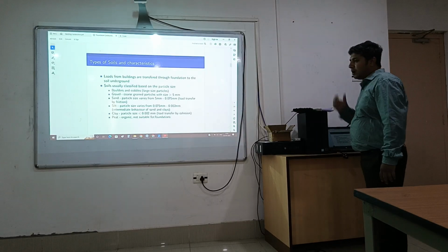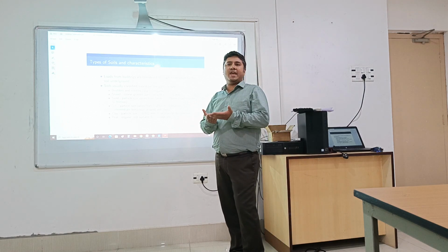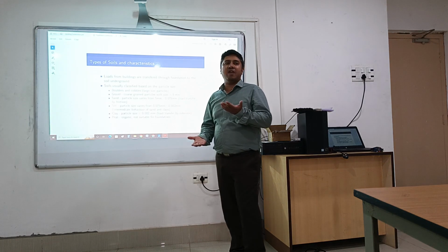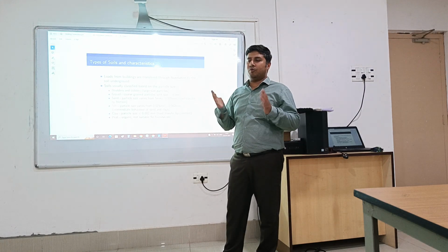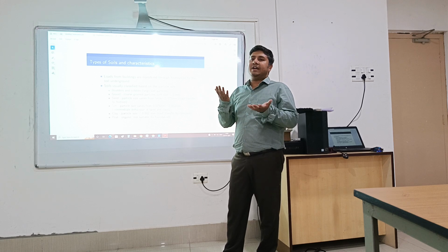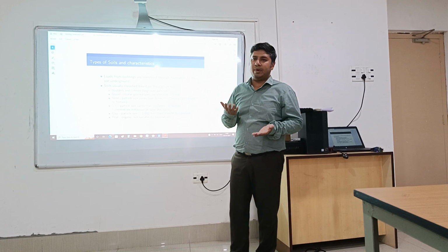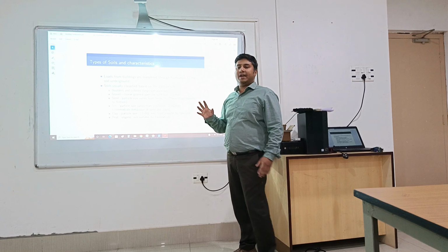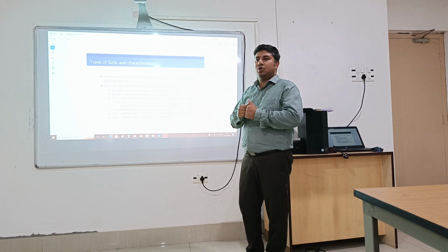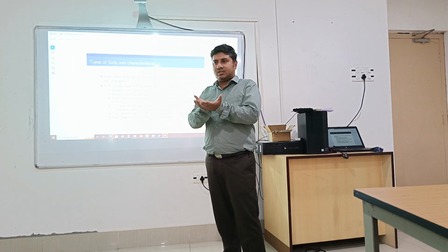So another primary requirement is that the foundation should be able to take the load and transfer it to the soil uniformly without differential settlement. It is not just to carry the load of the structure; it should also take the load uniformly and transfer it to the ground without any differential settlement. That is very important. That is why, not only isolated footing, but different types of mat footing or raft footing are used, so that our structure will be able to stay in the ground in a stable horizontal position.